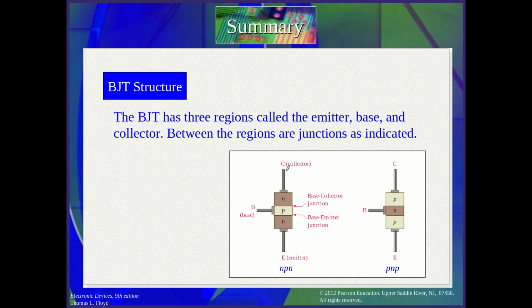Okay, so the collector current in Q2 causes the relay to be energized, because there is energizing here in this relay coil. Okay, when there is a light, then this is connecting to the ground, then there is a bias here that can't saturate it, or it can't be sufficient for a forward bias, and there is no IC current, then this coil is not energized.